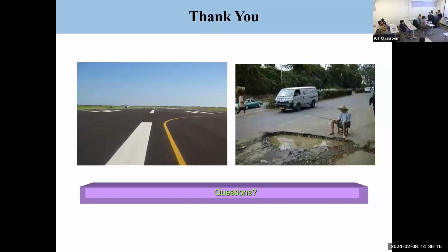If I may ask, whenever I think of plasticity, the yield surface, at least for asphalt concrete, is not really clear, right? For metals, we have done enough experiments to get the yield surface, and Drucker-Prager is very well defined for granular materials. But is there any way to identify the right yield criteria for asphalt concrete, which can include all these specifics?